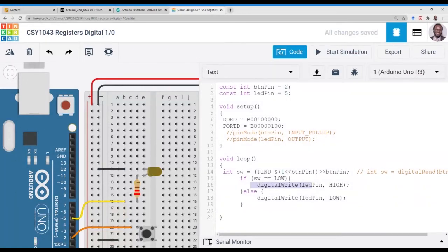Okay, so now we want to do some digital write, right? So digital write, let's write. Whatever value that we have here, afterwards we want to toggle it. So two things we are considering. How do we do digital write? Now we know how to read from a pin: we do an AND, because if it's a one, we get one. Now we want to do a digital write and then a toggle as well. If we have our LED and the LED is connected to bit 5, PD5, what we want is a way to use our reference, which again will be a 1, to the right bit position.